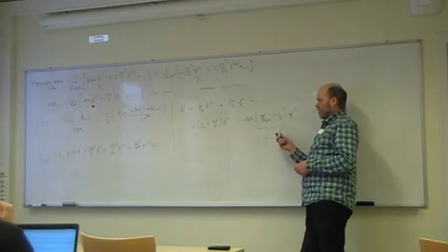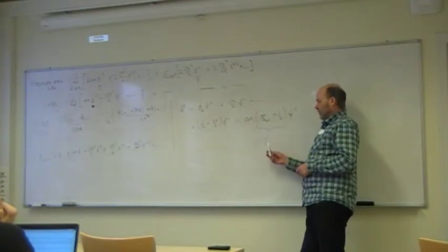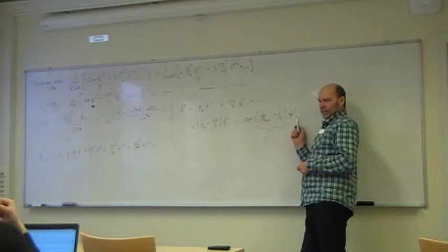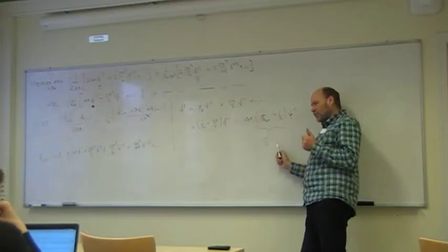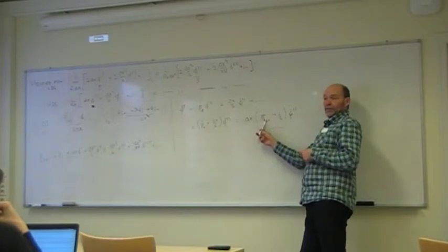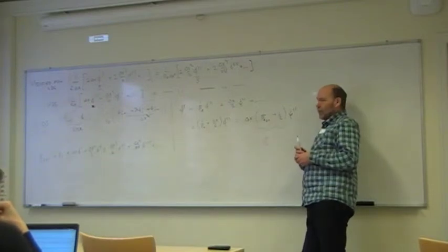If you start messing around here with a more unstructured mesh, 2D, 3D, you're in trouble. But yes, it should be possible to make this coefficient in front of the double derivative the Reynolds number you are interested in. Then you have to insert into the code a totally different Reynolds number, strangely enough. That should be possible.